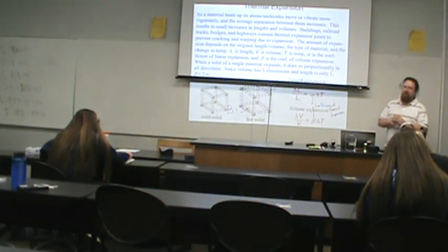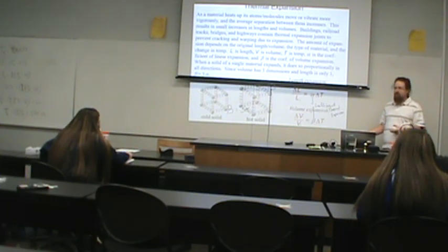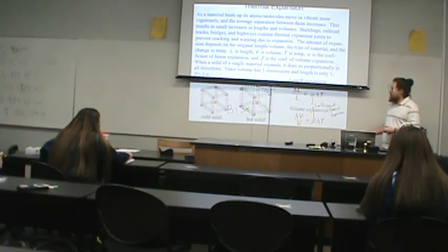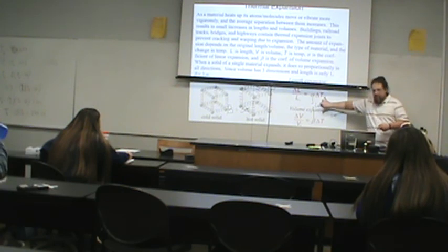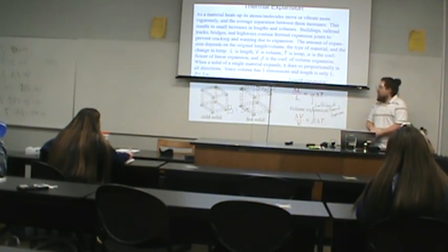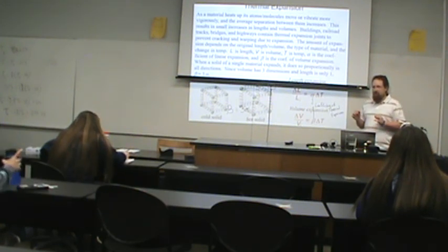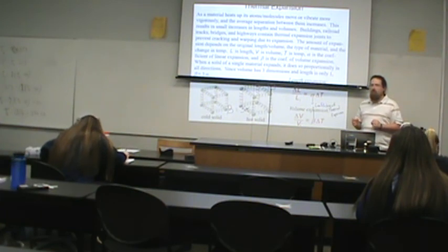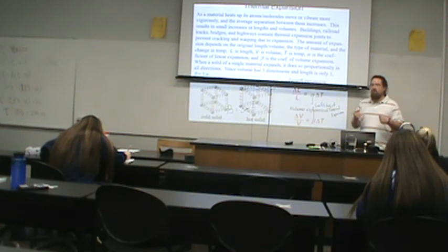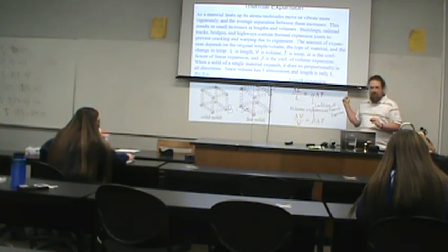So whichever one you're looking at, same principle, same basic formula, it's just a question of what it comes down to. And the one thing that's always the same across both is delta T. And it's worth noting that because this is delta T, the change in temperature, this is one of the formulas that you can get away with using Celsius or Kelvin in. Because the change in Celsius is the same as the change in Kelvin, since the units are the same size. The only one you can't use here is Fahrenheit.